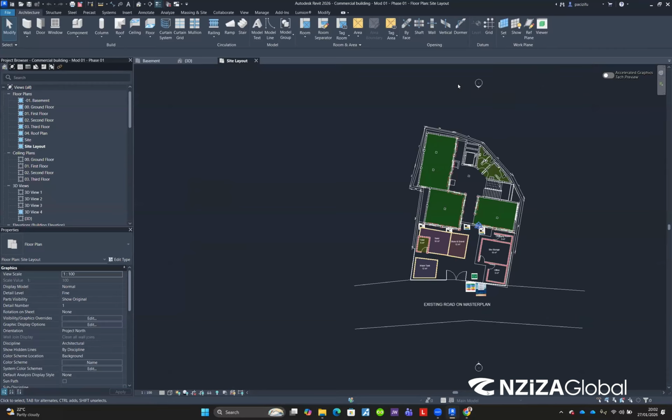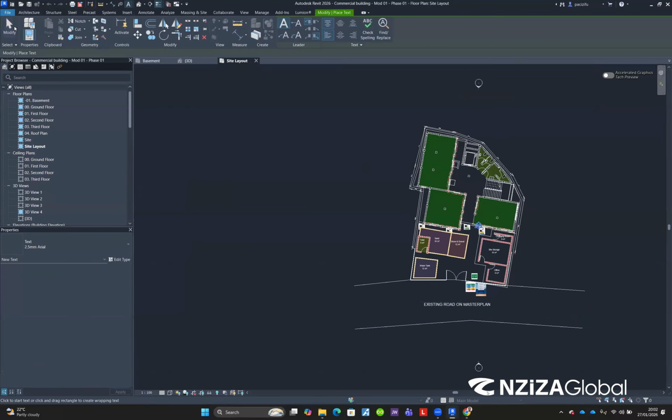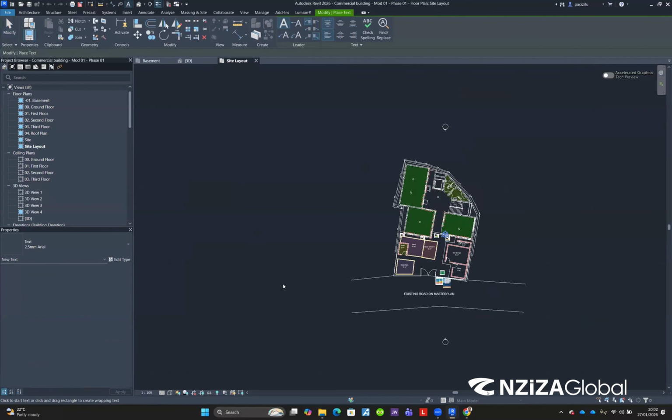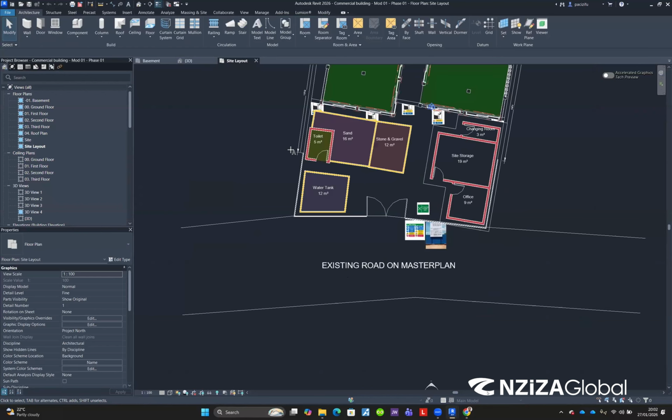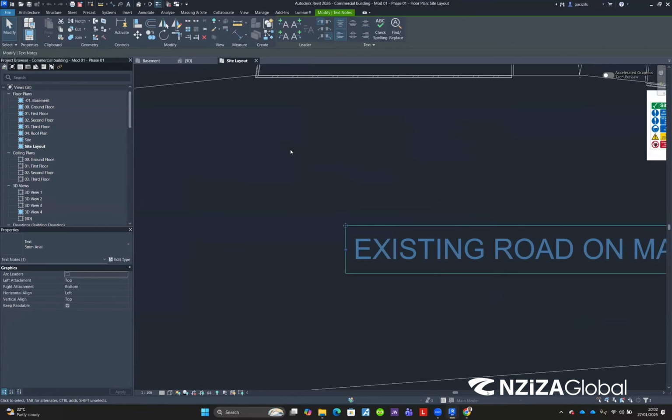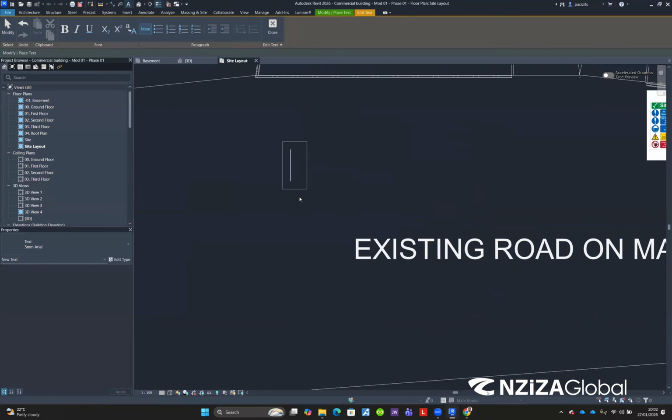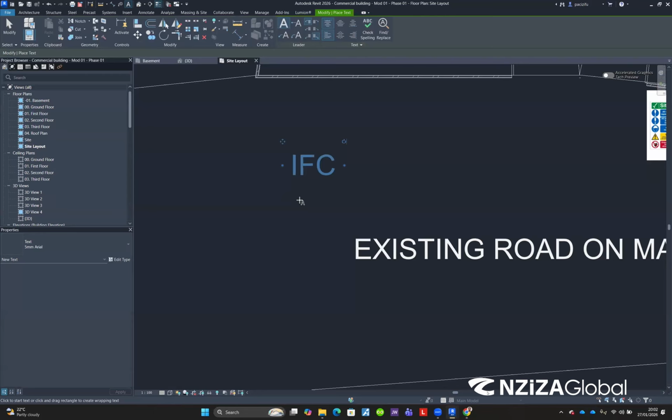You can just import it in Revit, but you will import it as an IFC file. We will find this kind of file named IFC when you are saving the project. Yes, you will save it as an IFC file. When you are using ArchiCAD, you can save that project in IFC, then you will open it in Revit.